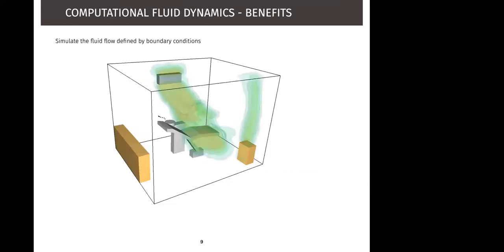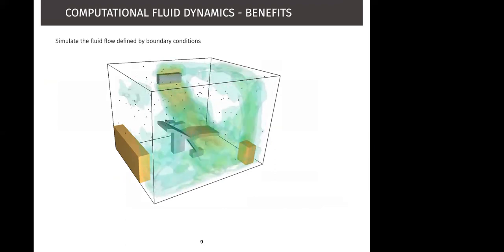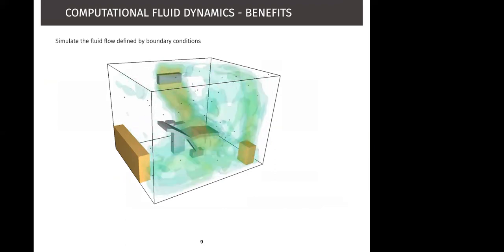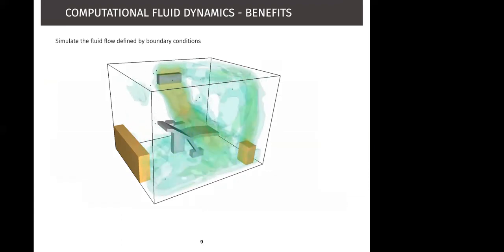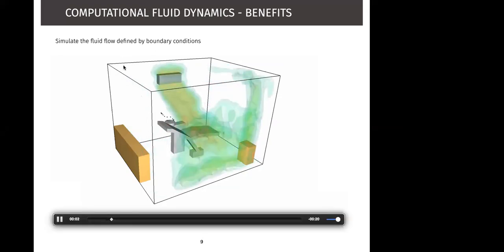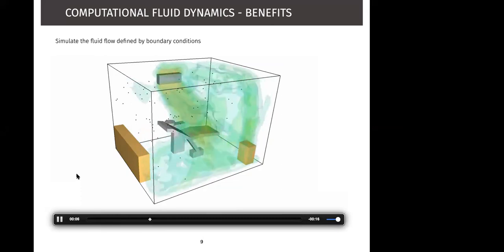Now, computational fluid dynamics gives you the same test, but you do it virtually on a system where you can put in your boundary conditions, which basically means that you can simulate airflow around the system in terms of the CFM through an air conditioner, or heat being added into the system or being taken out of a system, and you can see how the system is then behaving.